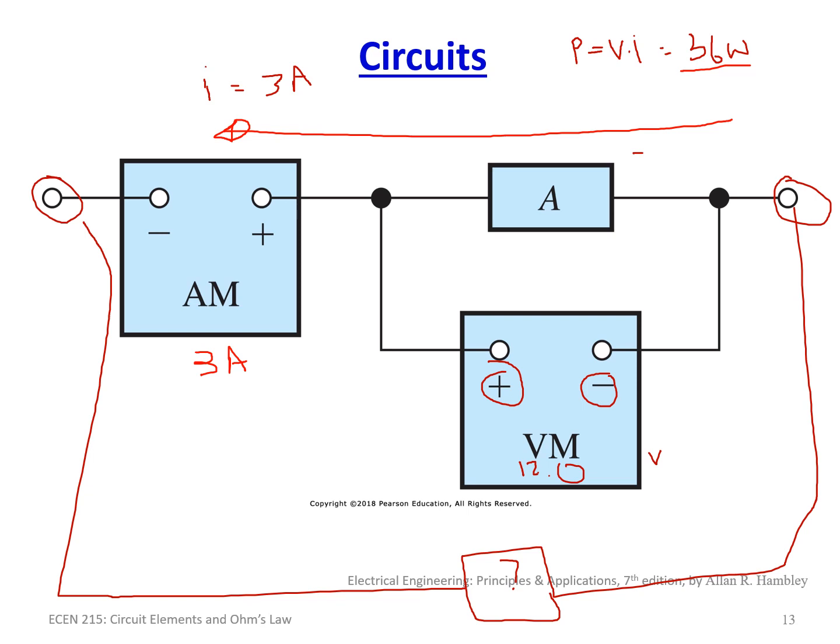Are we absorbing or are we generating? In this case, we're generating because now the current is entering the negative and leaving the positive. So this is where it flips. In this case, the current enters the negative terminal and is leaving the positive terminal of the circuit element, and in that configuration, it's generating. It's a power supply. So that's very important. You may get confused on this point, so watch this slide and ask questions, because this is where several students get a little baffled on whether something is generating or absorbing power.